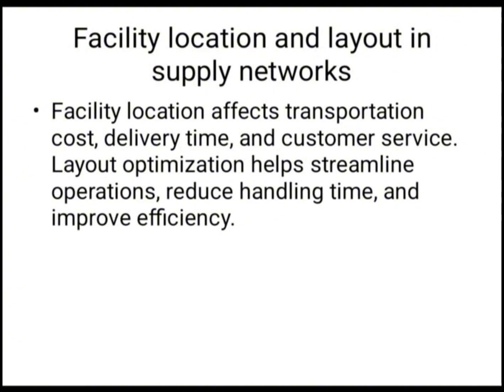And then also the facility layout refers to how the equipment, departments, and operations are arranged inside the facility. A good layout helps improve workflow, reduce movement or handling time, and increase efficiency. For example, placing related departments close to each other saves time and effort.